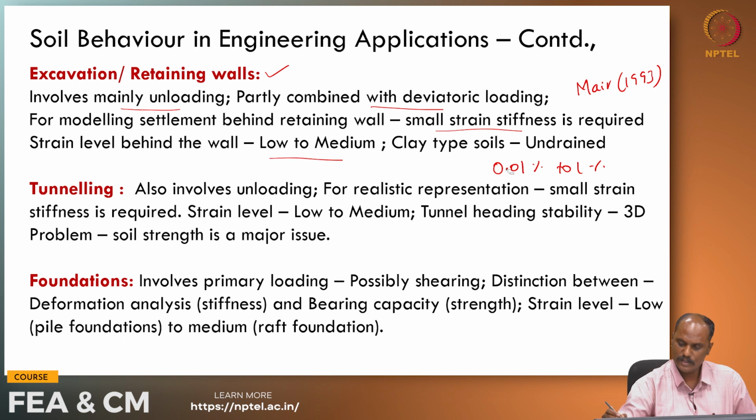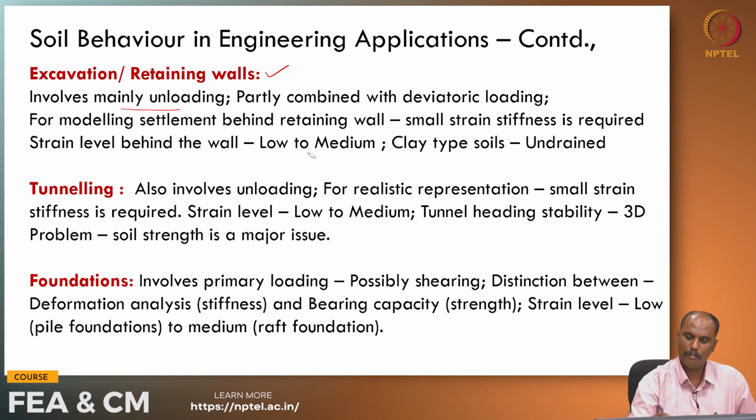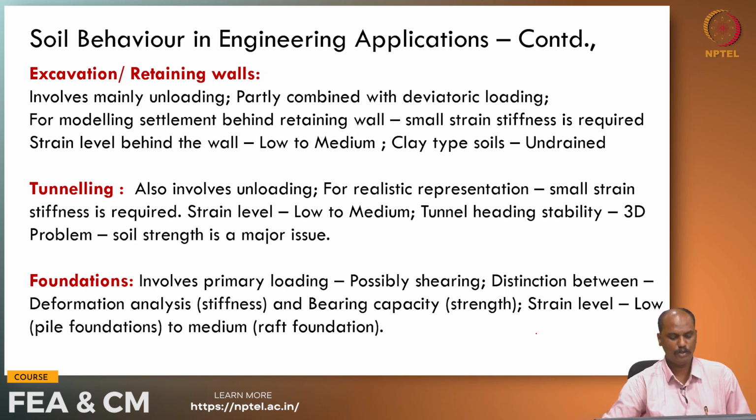So, when it comes to foundations, I would say that it involves primary loading and then possibly shearing also, and there should be a distinction between the deformation analysis and the bearing capacity analysis. The former, that is the deformation analysis, is concerned about the stiffness of the soil, whereas the bearing capacity analysis is more concerned towards the strength. And when it comes to strain levels, we have low to medium strain levels. For low, we have the pile foundations, and for medium, we have these raft foundations.